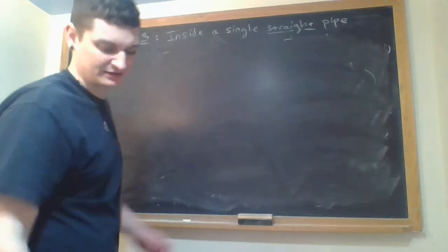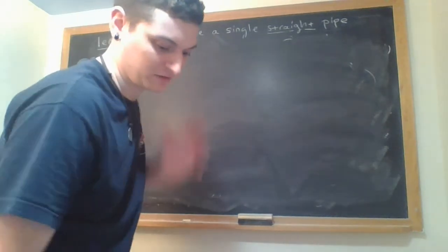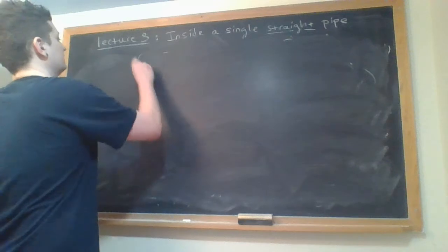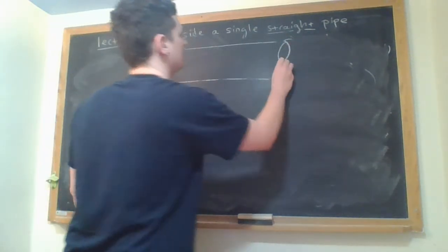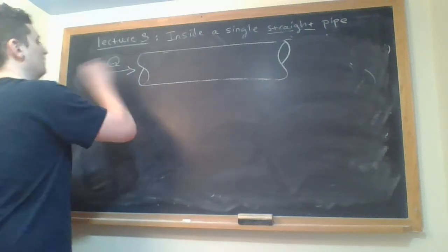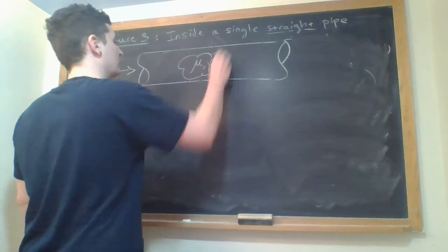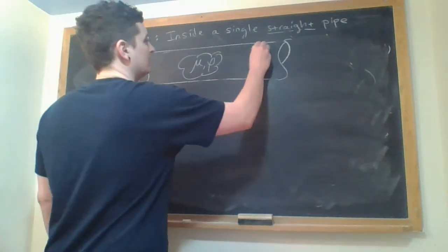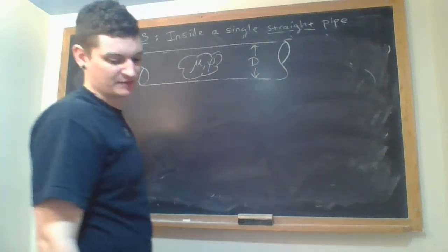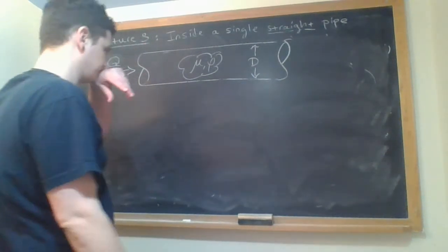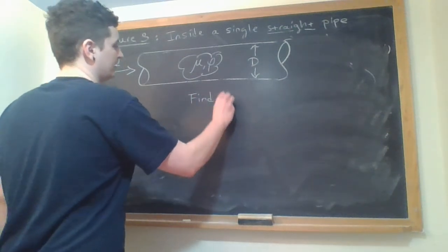So with that being said, that's going to finish this lecture and give an overview of what we now know how to do: given a pipe flow problem with a flow rate going into it, we have properties of the fluid. Let's say we know some dimensions, so we have some dimensions of the profile. So in terms of calculating friction factors, we find the Reynolds number,